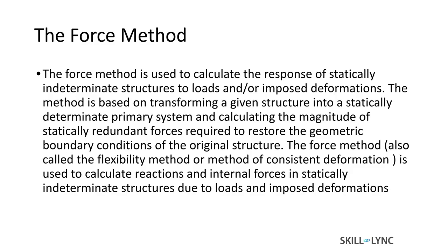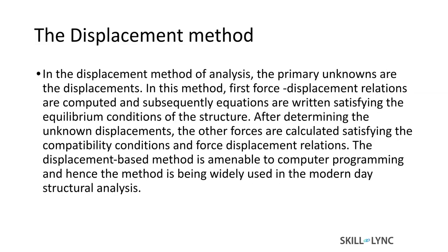I won't call it simple, I'll call it a single formula. So when you input your structure or the boundary conditions to this program, we will arrive at a degree of indeterminacy that will help you proceed with the force method, set up the force matrix and displacement matrix to arrive at the response of the structures.